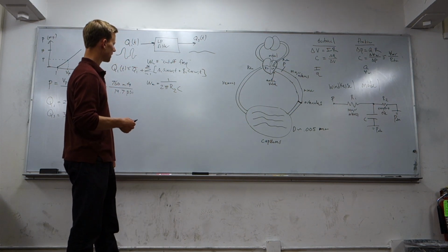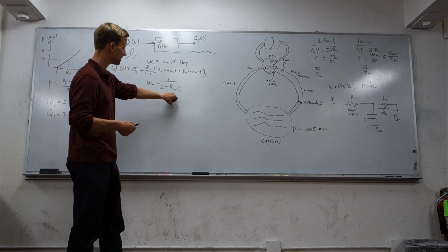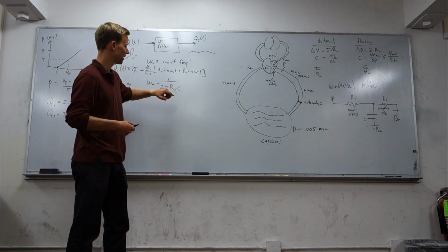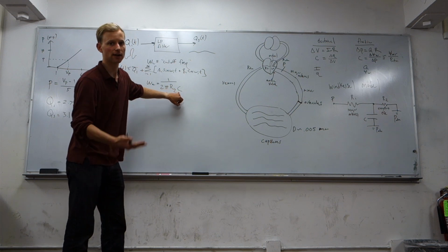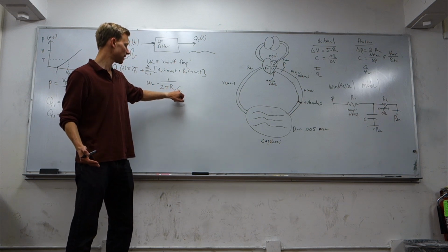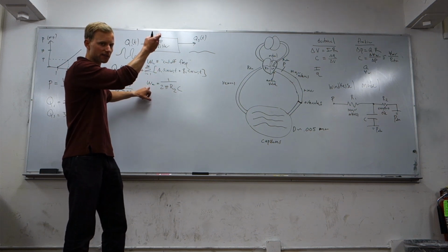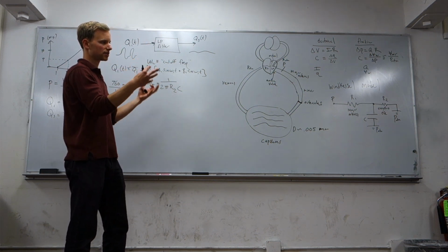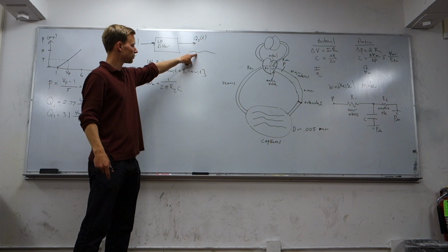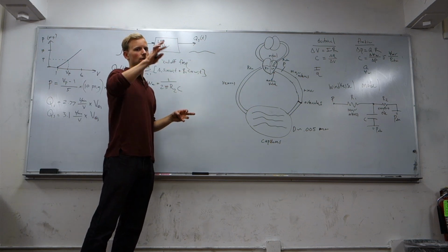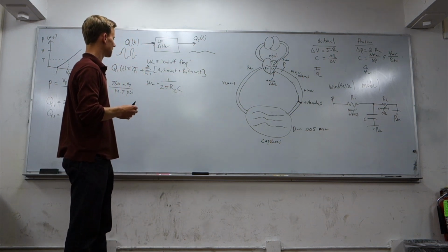Okay? And keep in mind what will happen if we change R2 and C. If we change C, let's say we decrease capacitance like we did just a second ago, omega c goes up, so our cutoff frequency goes up, and we're a low pass filter, so we're allowing more of the input signal through. So this Q3 will end up being more pulsatile, have more amplitude swing.